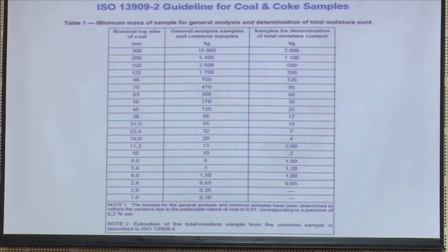But make sure that when I am breaking the particles, the surfaces become very active. So, the reactivity of the surfaces will be more, and there will be a chance of chemical composition changes. So, I must store it properly. Specifically for coal, it gets oxidized very fast. So, if I am bringing it to some place and I plan to do the analysis after 7 or 8 days, you make sure that it is free from oxygen.